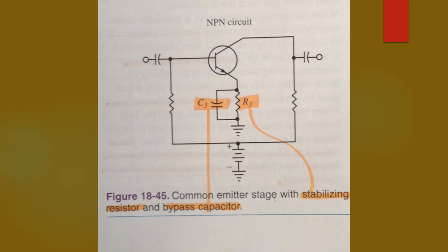Thermal considerations. Transistors are easily overheated. As operating temperature increases, there is greater thermal activity in the crystalline structure and a decrease in resistance. Repeated resistance decrease and current increase can cause destruction of the transistor. This condition is called thermal runaway.